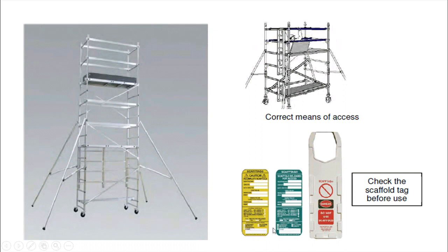But if this is on green status, that means the scaffold is safe to use, but you need to make sure that you are complying with safe procedure of using the scaffold. But if this is on red tag, that means no one is allowed to use such scaffold until it has been rectified by the competent persons and the green tag is put on it.